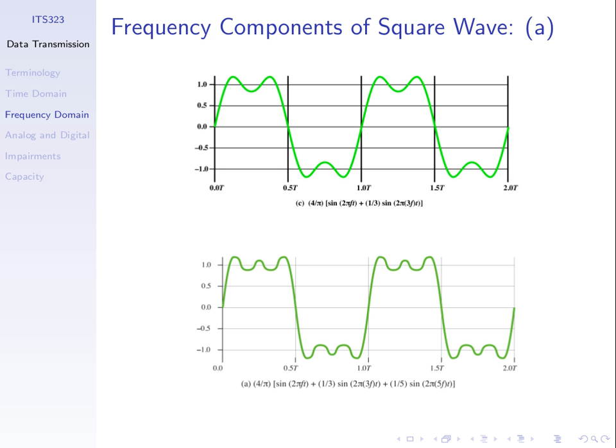The problem with signal B is that it uses more bandwidth. Now bandwidth, the range of frequencies which we can use, is limited. There's only some frequencies that we can use. And how it actually works in practice is that governments control which frequencies you can use for which purposes. Because there's competition, that is, some companies want to use the same frequency, it turns out that frequencies have some cost involved. The larger the bandwidth or the larger range of frequencies you use for your signal, normally the larger the cost involved. We want to minimize the bandwidth we use, smaller bandwidth, but maximize the data rate.